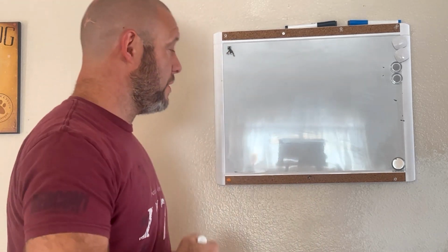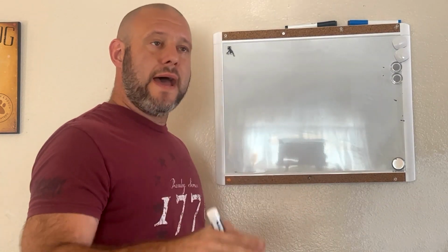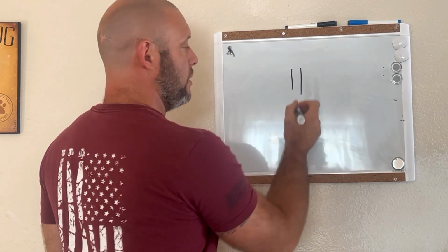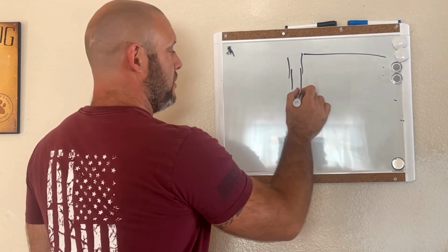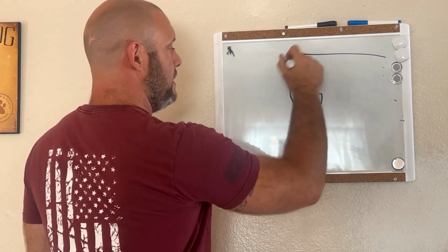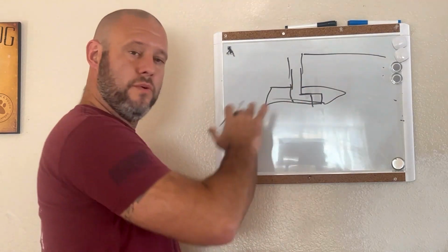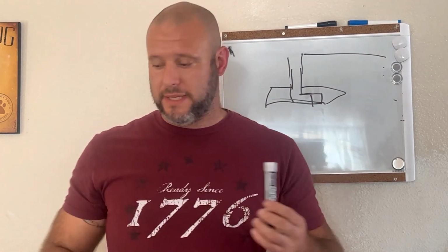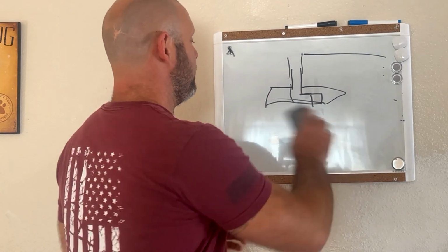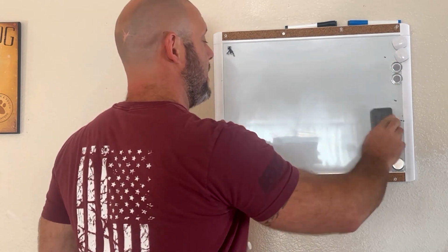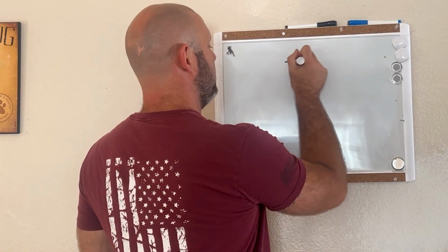Anyway, going into it. When you design a retaining wall, right, and I was mentioning before, you need to have as-built drawings as to what this retaining wall looks like. Let's see, hillside there, right? Is it an L shape that goes in toward the hillside? Is it an L shape that goes away from it? Is it a T? What is this, and what are the better means and methods to do it, right? Because that's going to change the approach. Okay, so there are a couple of different types of failures that you have when you have these types of things. Which one is the better model?